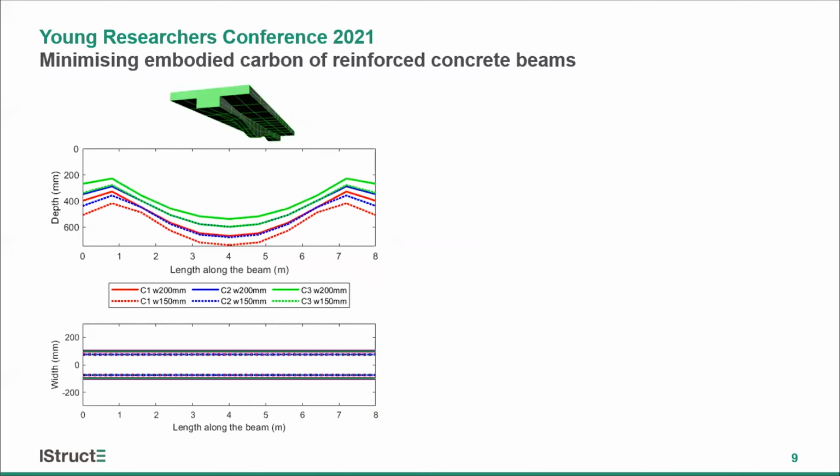This graph shows the outcome of theoretical optimum shape finding for 3 different load cases for 2 choices for the minimum possible width. As you can see, even if the span is the same, the optimum shape has depended on those 2 criteria. The problem here is the outcomes from theoretical optimum shape finding have resulted in depth profiles that have positive and negative curvatures.